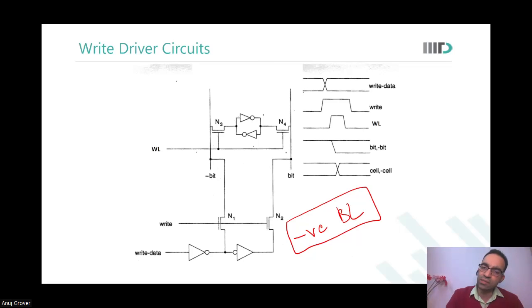So there are some capacitors in advanced write drivers. You will see that there are some capacitors that are also put there. There is some tracking circuitry that you may want to put there, so that whichever side you want to write a 0, on that side, after 0 has been written, the capacitance is triggered to generate a negative bit line. Okay, so this is a very simplistic view of a write driver, and for top level understanding, that is fine. But when you enter your projects and make your write drivers, then you have to take care of being able to generate negative bit line also.